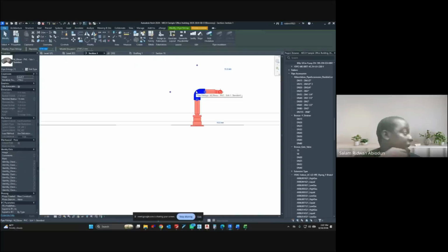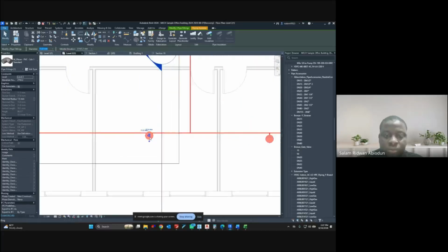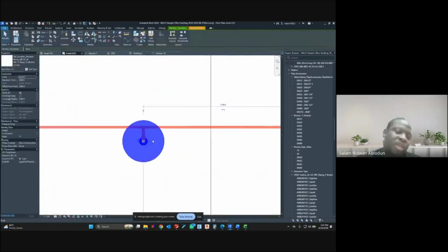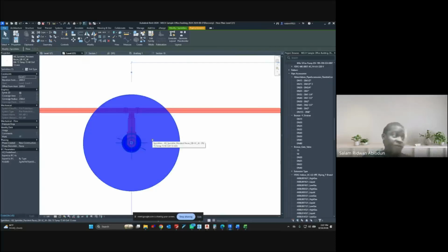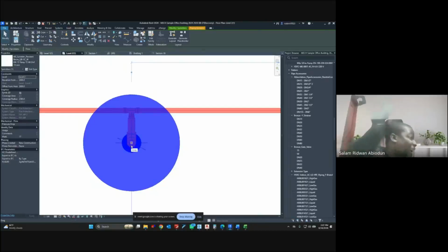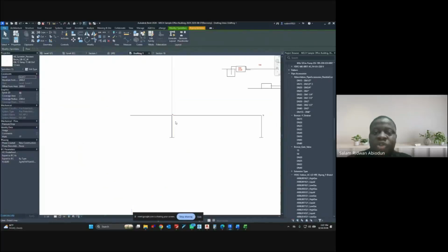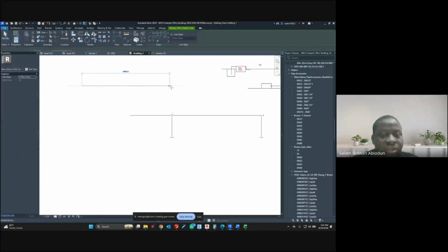So this elbow is what we are accounting for. There is an elbow. Sorry, I'm getting confused somehow. Okay, the reason why it's showing an elbow is because it is off. Look at this place. It is off before now going down and dropping to the sprinkler. It's not as if it is coming down from the sprinkler. Do you understand, Victor? There's a difference between something dropping from the header directly to the sprinkler and having an initial T, then dropping down.